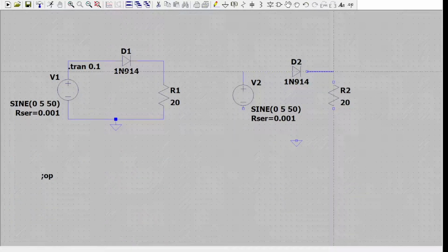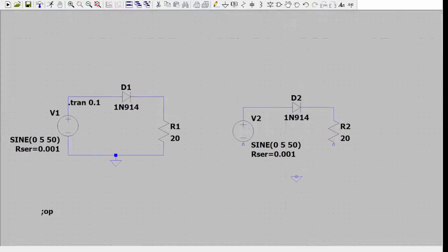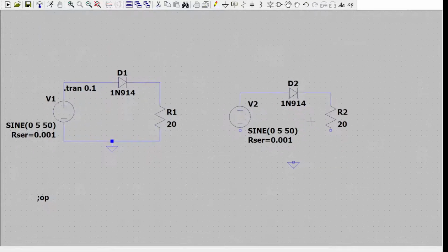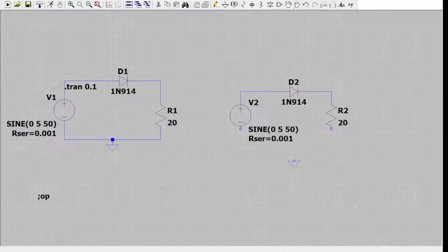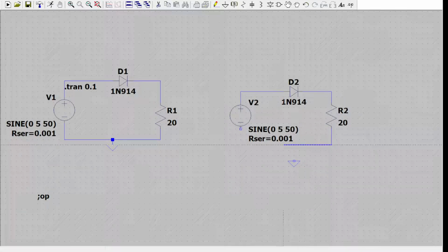So all the components and stuff that I'm pulling from right now, you can find them all up here. I'm sure there are images online labeling this toolbar. For example, if you wanted to move a component, you would click drag, click it, move it around. For wire, click wire. It brings up this crosshair, and you can just click, drag, click again. Just draw your circuit.